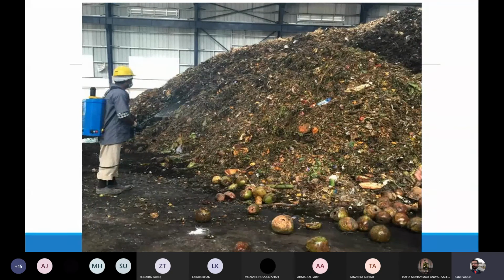If you are receiving a lot of waste on community level on a daily basis, you must have the shredding process in place so that all the waste is shredded, and this would reduce the total time period of biodegradation, because you already have the waste at a uniform size. You can also add moisture content to enhance the biodegradation process.